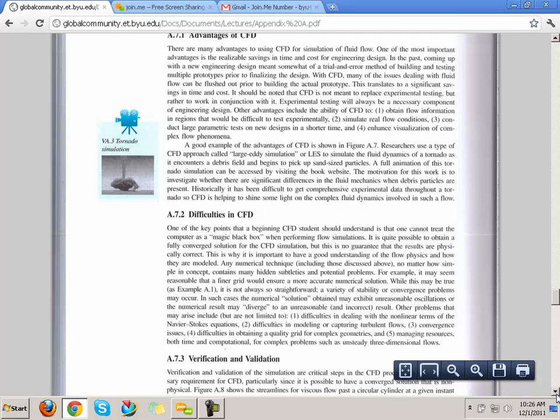And they'll tweak the CFD simulation, like the slipperiness of the surface of their object, or whatever they need to do, until they can get their CFD results to match what's actually going on. Once they have that, then they know that they're getting accurate results, and they can start ramping up the speed and doing different things because they know it's now reflecting reality. So just out of the box, if you just run a CFD, it may not actually be reflecting reality.